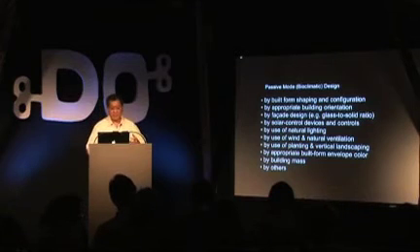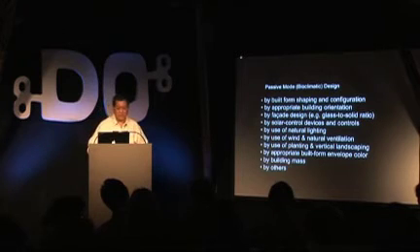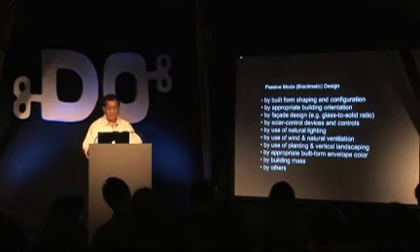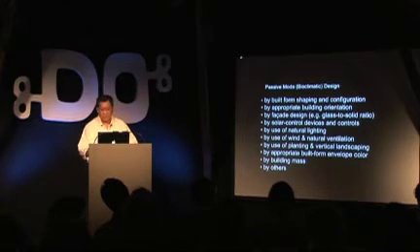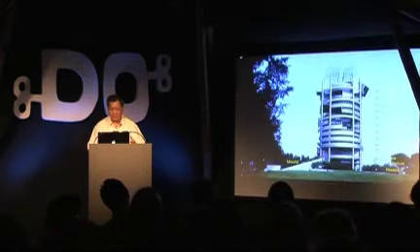Now, bioclimatic design has to do with shaping and passive systems. For instance, proper shaping of the building and orientating it, proper facade design, good glass to solid ratio, use of solar control devices and sun shading, use of natural lighting, use of wind and natural ventilation, and so forth. These are different ways that we can actually improve the energy performance of the building, and we should optimize all these options before we do anything else.